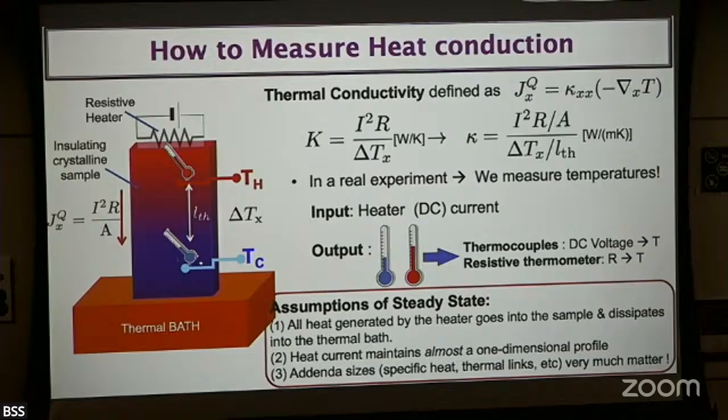So how well is the thermometer attached to the heater? When we measure our body temperature, we just put the thermometer under our tongue, and it's pretty well attached, I would say. Also, in that case, the heat capacity of my entire mouth and body mass is much bigger than the tip of my thermometer, so the thermometer's is small. And it was very well attached. So how well attached it is, that's actually really important.